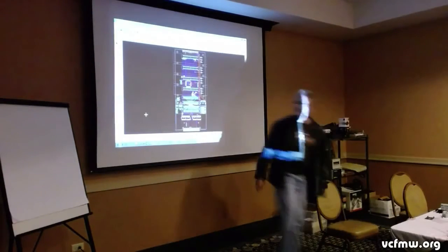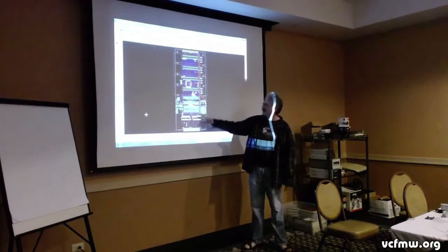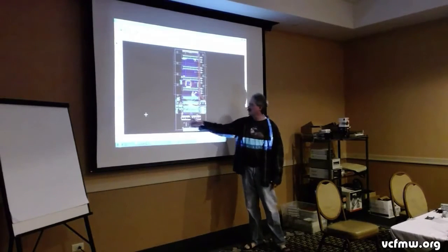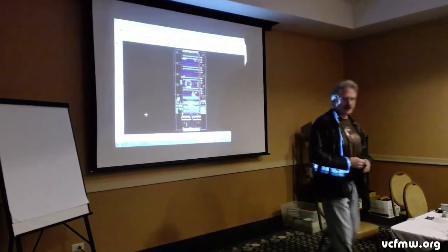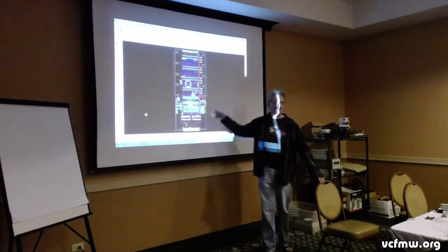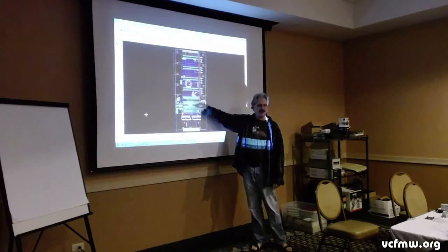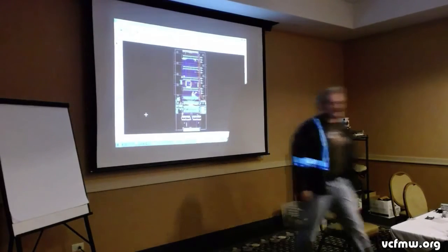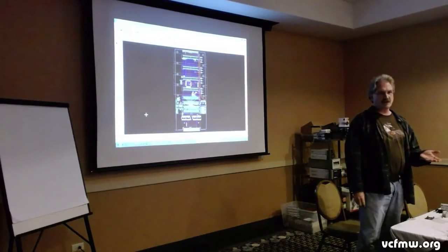So there we go. Some buffer chips down here. In this particular case, it was easier to put some dedicated buffer chips right here just to make sure that the signals are all nice and cleaned up. Predominantly for 2 reasons, not just for the CPLD. In this particular case, these 2 boards are separated by a long cable, and so the buffering helps with signal integrity. But you can buffer, you don't have to, on the 3.3 you have 5-volt tolerant input.